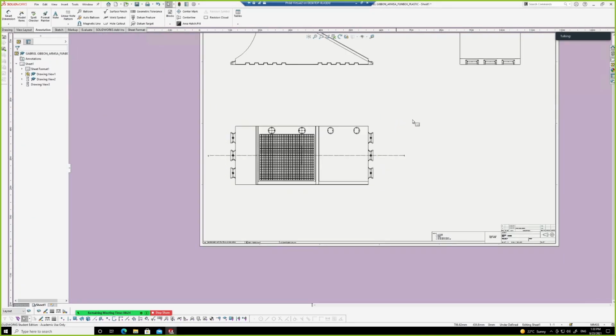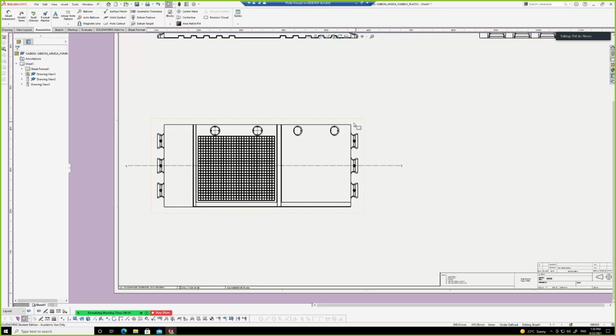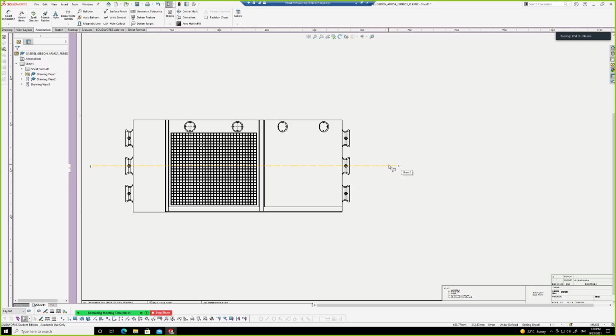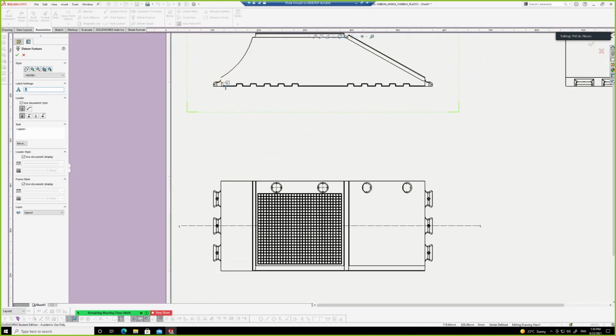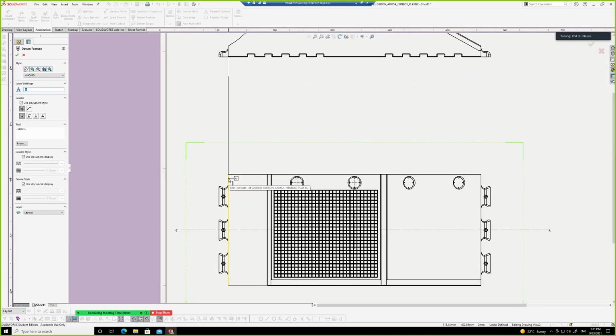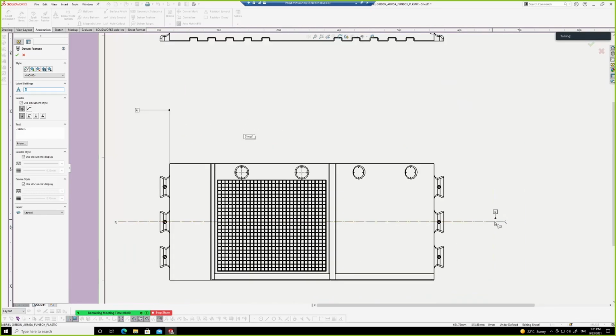I'll try not to deal with irrelevant detail, but these are all important things. Now with that center line in place, you're going to dimension everything relative to the center line, because the center line makes sense as your one datum. So let's put those datums in. One datum is here, which I'm going to put in this top view. The other datum will be this one.